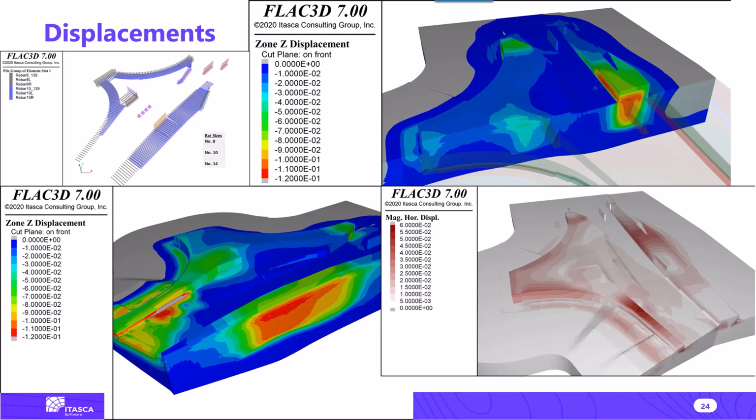Keep in mind that, as I was mentioning at the beginning, in order to improve the lateral stiffness, we put inside the embankment, you see on the upper left corner, internal rebar inside the embankment itself. These internal rebar are made of steel. Once the embankment wants to expand laterally, it is essentially constrained by this internal rebar, and this really helped to control the lateral deformation for the column that would have been essentially incompatible without these rebars.